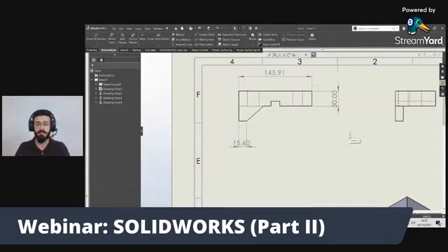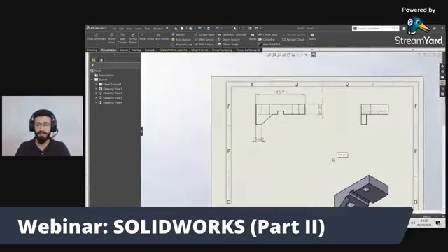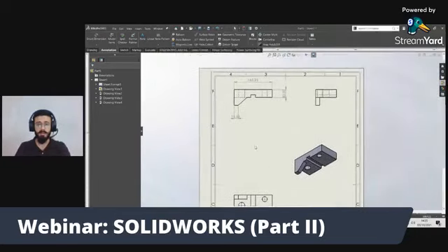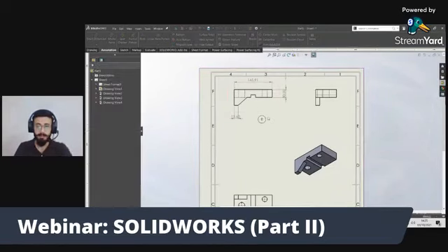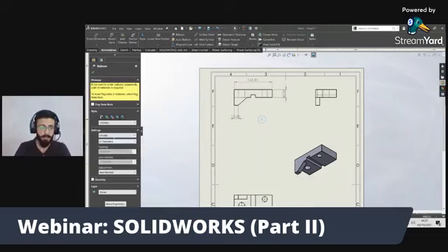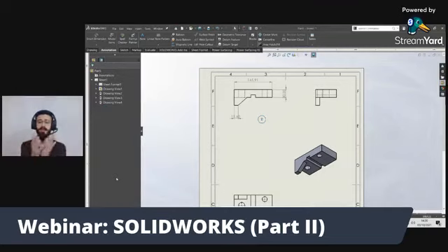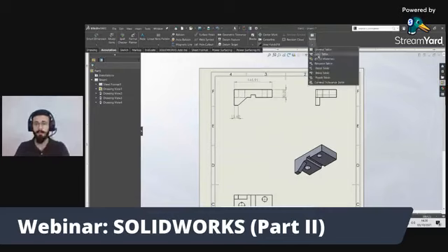This is the style I mostly use. You can change the arrows, you can change everything. And now you can also add mark balloons. You can change the balloon also here, the item number, and you can add a text or anything. If you want to add remarks, add some kind of symbol or that. And the next feature the 2D drawing gave us is tables. You can add bills of materials.